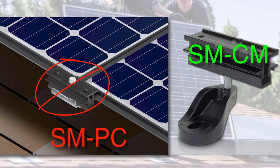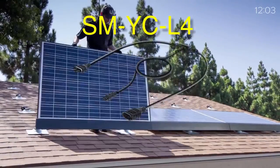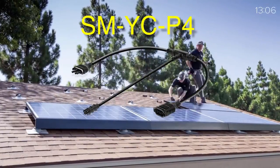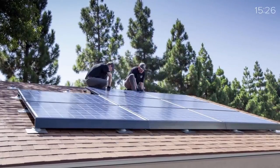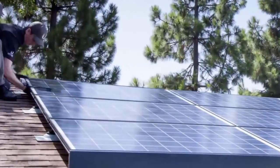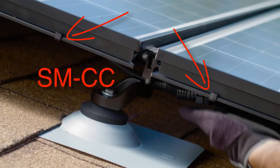On rare occasions, connector mounts substitute panel connectors in the event that a mounting assembly coincides with the spot of a panel connector. Using portrait and landscape Y cables, continue connecting rows of adjacent modules. Using jumper cables, connect different rows of modules. Cable clips hide and protect all trunk cabling throughout the array.